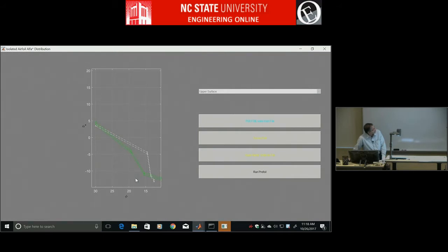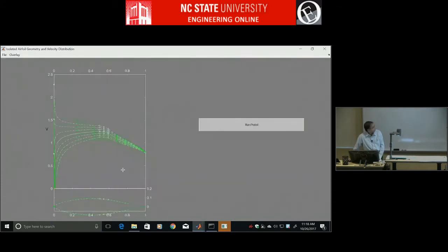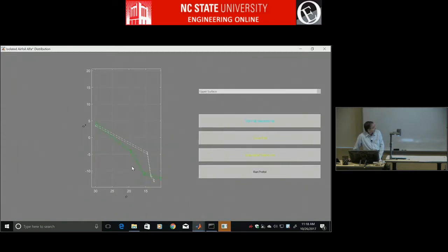One of the glitches with this is once you zoom in and then run profile, that zoomed in plot becomes the default. So I can't zoom out now any more than this. It's okay. This is segment 1, this is segment 2. This is segment 1, 2, 3. I want to make 3 more favorable and 2 more adverse, right? I want to move this up and maybe leave this as it is.